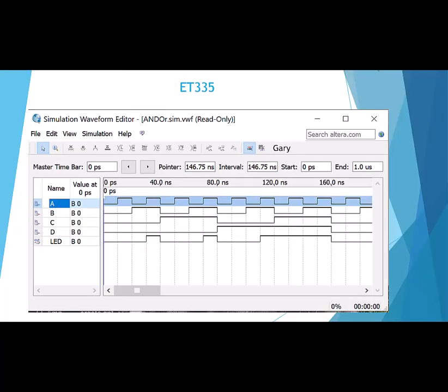Okay, let's take a look at our AND/OR wave here. And we have 4 inputs, so we're going to get 2 to the 4th power equals 16, and we're going to go from 0 to 15. And we're going to go through and we're going to have a binary count. So let's just put 1s. Yeah, all the other ones are obviously 0s.